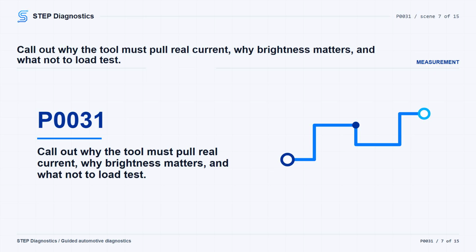If bulb brightness is questionable, voltage drop across the 3156 bulb can confirm what the circuit is really carrying. As an example, 2.0 ohms of resistance in the circuit being tested will cause the voltage measurement across the bulb to be 25% less than when compared to battery voltage, because the 2.0 ohms in the circuit makes up 25% of the total circuit resistance of 8.0 ohms. Keep components disconnected during load testing, and do not use this load test method on restraint system circuits.